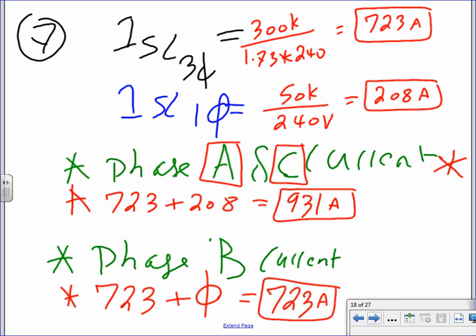Any comments, guys, any questions? I can't emphasize enough, guys, these are the amps they're going to be using to size the fuses and the circuit breaker. That's why I highlighted them in the standalone sheet. Moving to number 8. Any comments, guys, about number 6 and number 7?